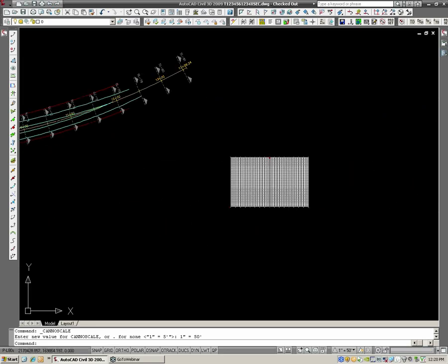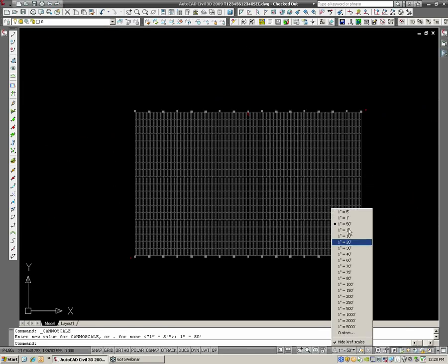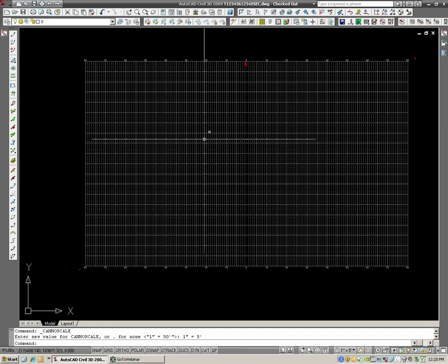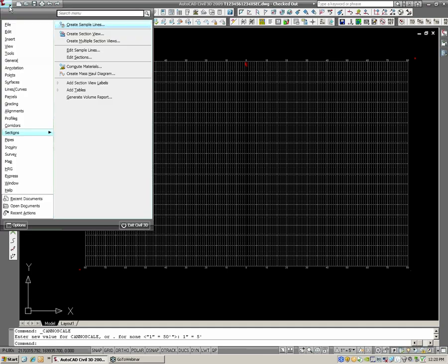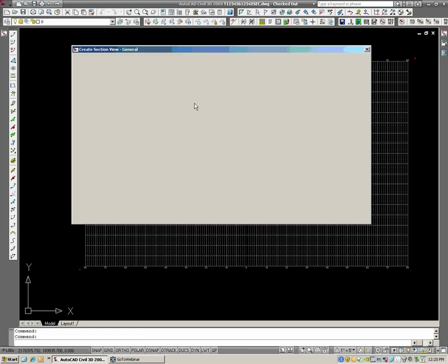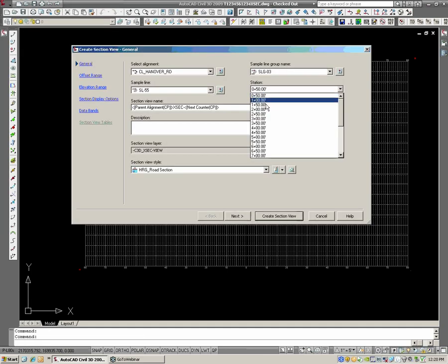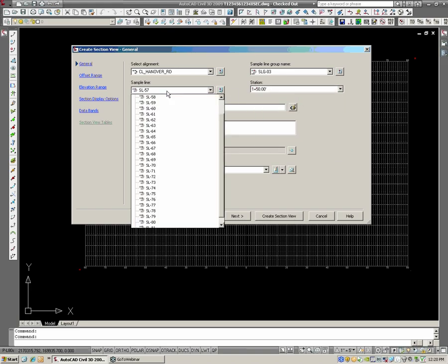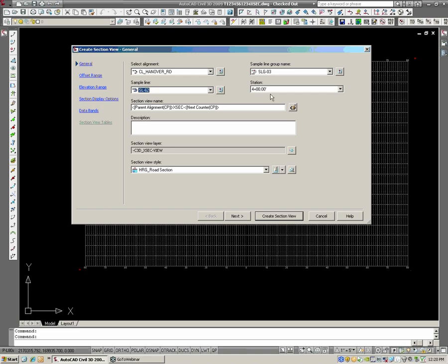If I go back over again, change this back to 5 before I plot it. Notice if I change this to 200, it's going to be 58. If I change it to 150, 57, vice versa. If I change this over here, it automatically changes to the station. So I'm going to change to station 200. Pretty much everything else in here should be good to go for you.